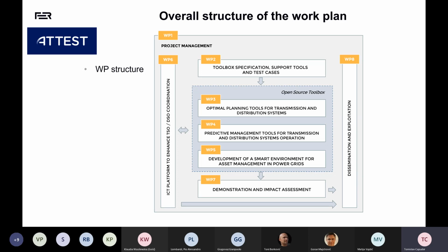So this is very complex. You actually have very, very complex optimization tools being developed here. So we are developing so-called optimal power flow, AC optimal power flows on a day ahead and in real time for both the transmission and distribution system operator and trying to coordinate them. We have a tool which is dealing with the state estimation, and we have a tool which is dealing with the online security assessment, so that you actually can assess the needs for frequency services.